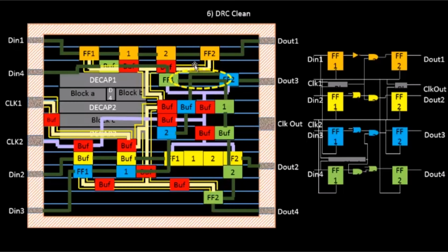So this is what we do finally when we try to do a DRC clean. And there are other problems while we try to do DRC clean. For example, with the existing route, a timing estimation had been done, but due to the DRC clean step, the routes might move to other places, and the wire estimation will change, and as a result, the timing will change. We'll talk about all this in the DRC step. This is an overview. We have to do this step after we do a route.